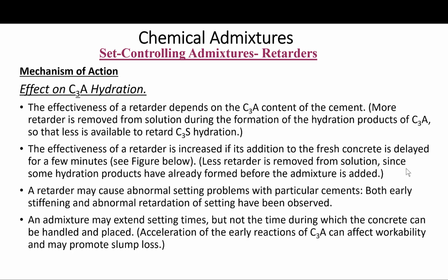Okay, number 4, an admixture again may extend the setting times, but not the time during which the concrete can be handled and placed. So acceleration of early reactions of C3A can affect workability and may promote slump loss. So a retardant admixture may influence the behavior of an expansive cement. You remember? Where the rate of formation of ettringite is changed. So again, using such an admixture with special cements has to be investigated with care and thoroughly.